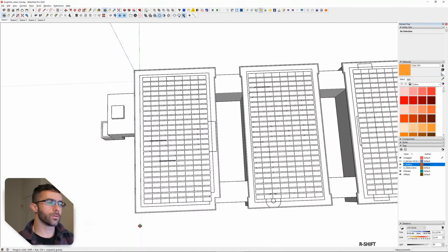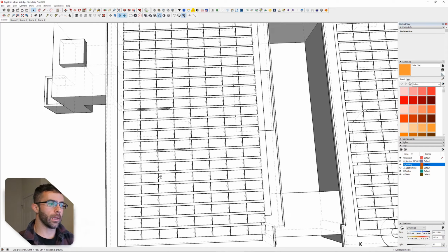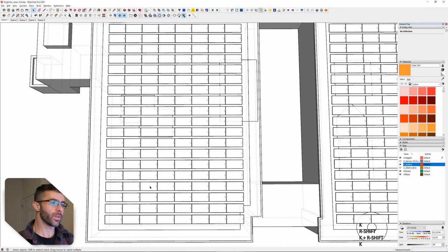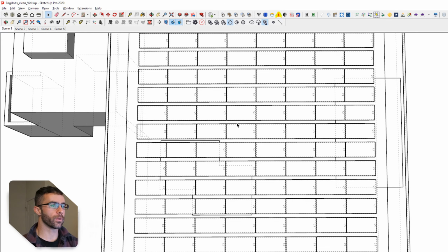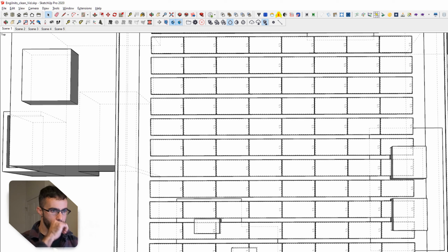All right, so to avoid the offsets, you can hit K in SketchUp. That brings up this hidden line option. Let's see if I can make this just a bit higher res or bigger for you, in case you're watching it on a phone. So you can see the dashed line show up of our equipment offsets. If we bring the obstructions in, it becomes even more apparent. So obviously you can't have this module and this module because they're through a piece of equipment. Same here, those have to go.